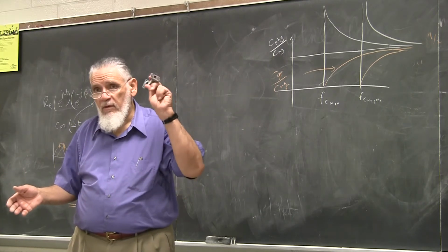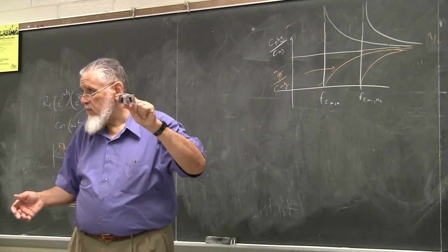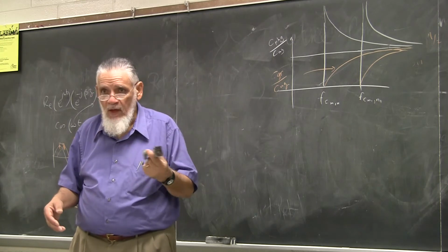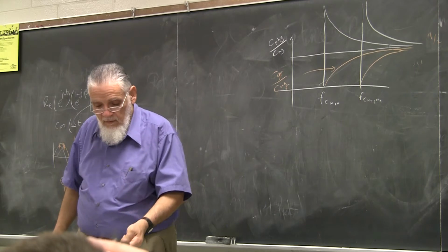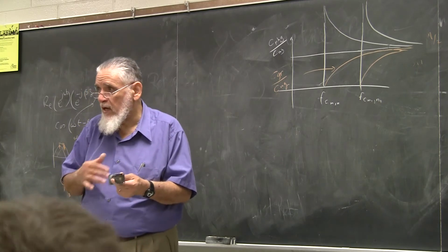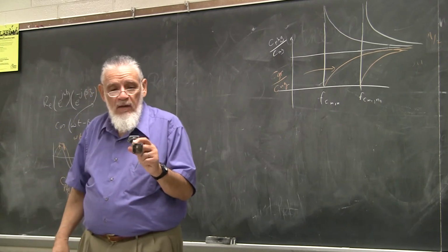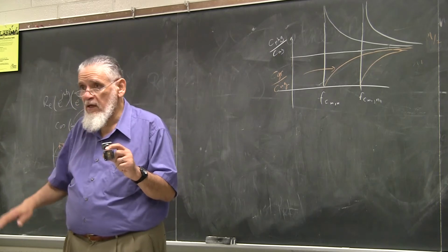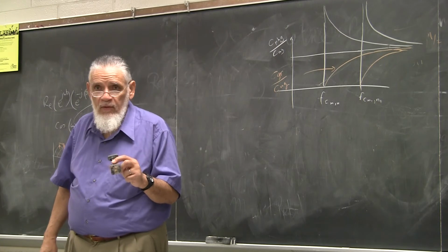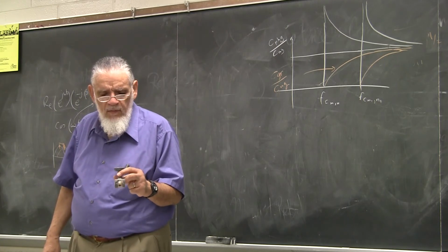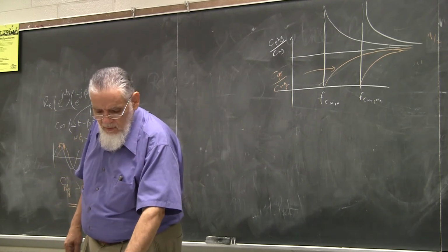Even with vacuum, or free space guides or air guides, you still have losses because of the finite conductivity of the surface. That's why the inner surface of the guide gets to be polished, very neat, and sometimes either silvered or gold, typically silver, to make sure that we have the best conductivity.